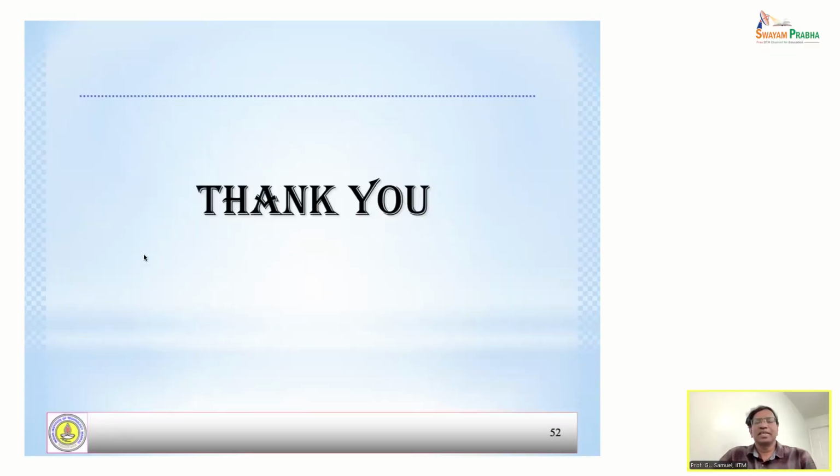Yeah, programming actually, you see, our laser machine also has software. It's a customized software for that particular setup, called Kaila, where we can give the geometry. Based on the geometry, it will automatically move. We can't control it manually, because the laser is very fast. So you program it here, the XYZ coordinates will move according to that, and then they produce the shape.